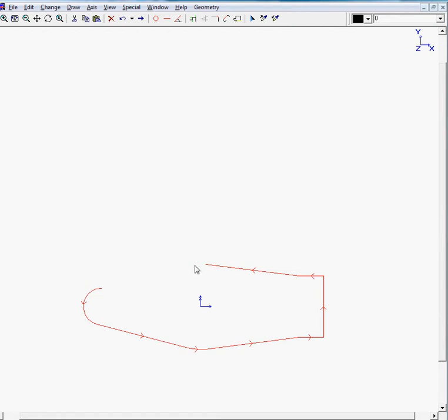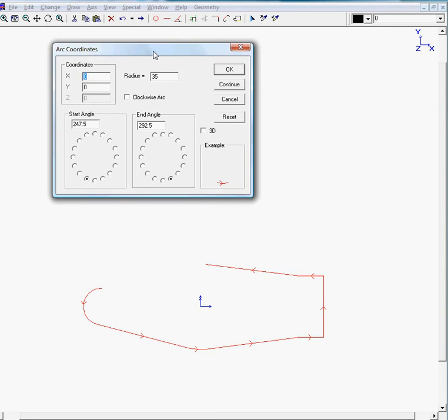As you can see, the R20 is a fillet between this last line and the radius of 100, and of this last arc we know all the geometry. The center of the arc in X is, let's see, is -80 plus 200, which gives you 120.